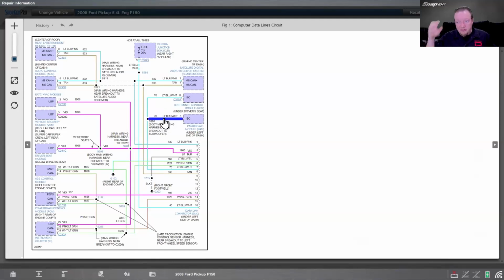So it seems like, interestingly enough, the power wire, this ISO wire, and so those two are light blue with white. So it's either power or it's communication line. So interesting. And you notice we also have these junctions here. They have joints. So these could fail feasibly as well. So if I get signal from here all the way over to here, but then I don't have signal here, but I do have signal here, then I'll know it's probably this one, right? So being able to interpret the wiring diagram to see where everything is can be invaluable.